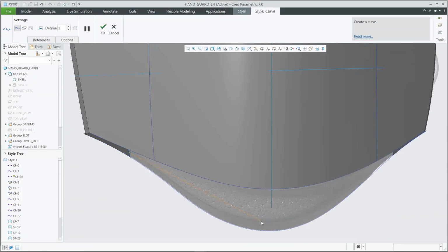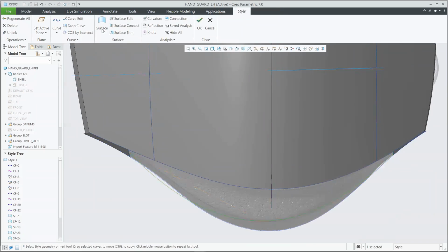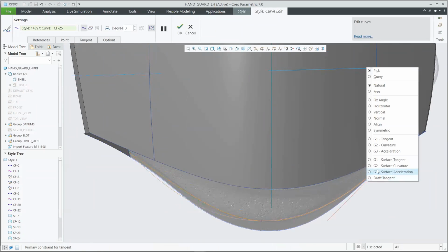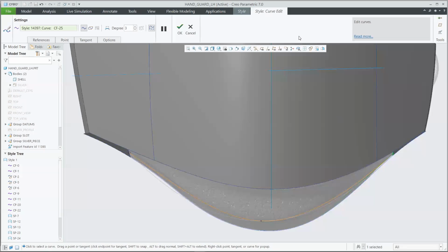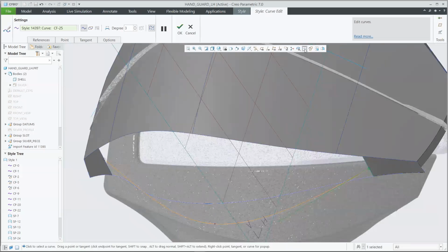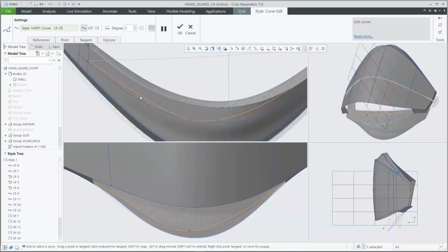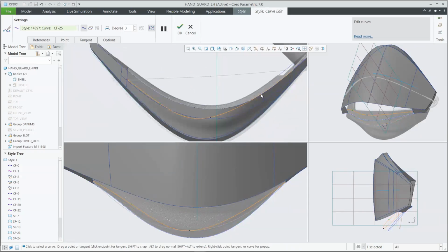And as you can see, that quick menuing that I'm using here for defining the tangency and the curvature while you're working, it's very fast, right? It's one of the main points throughout all these different tools that we have in ISDX, whether it be the multi-section view, the quick menuing. We really created a tool in ISDX that allows you to build out some fairly complex geometry, but do it in a way that takes less mouse clicks, less hassle to build things out, and still have a lot of control throughout that process. And here we're just making sure that our center curve is aligning well with the initial sketch that we started with.